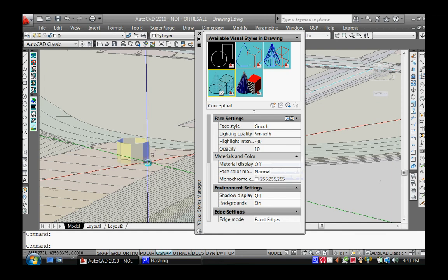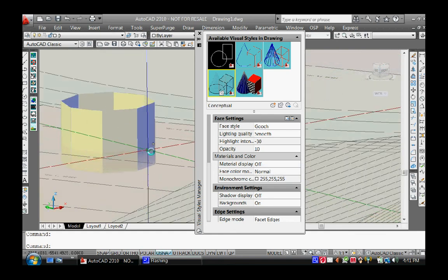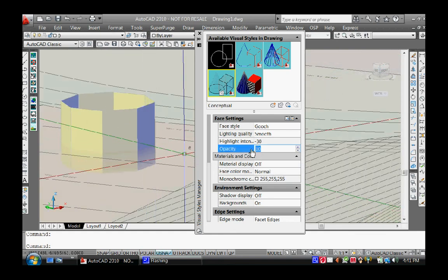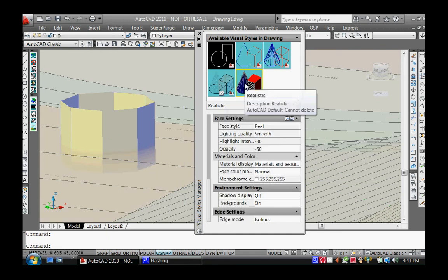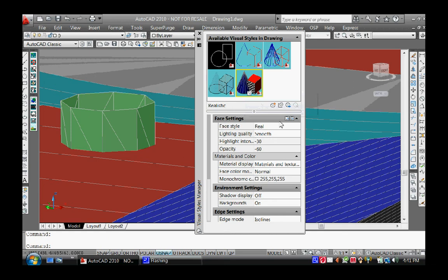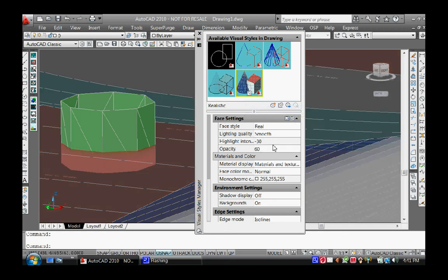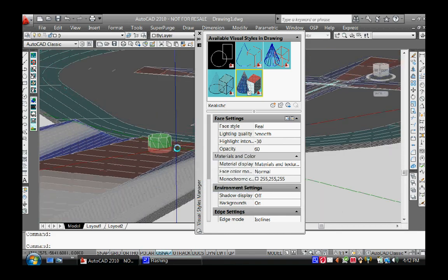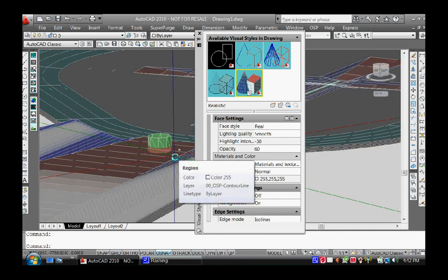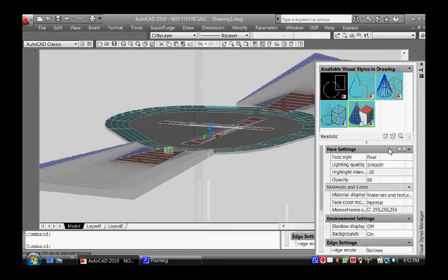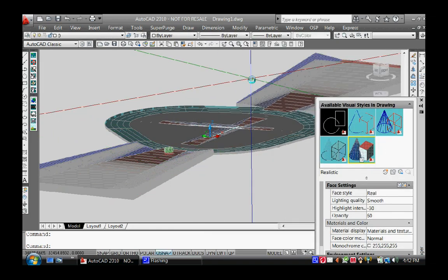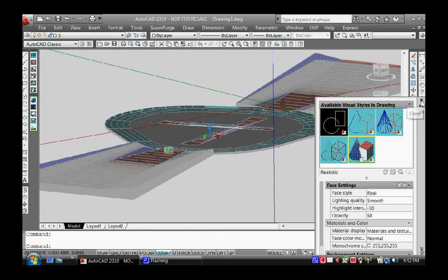You can kind of see the surface penetrating. Again, you can play with the colors and make this as fancy as you want. We can even make it conceptual if we look at the object that way and, there we go, give it an opacity of about 60. Something like that. You can see the object through the surface, and again, you can get as fancy as you want. You can put images under it. The program will detect different types of mountains. It'll detect any type of 3D object that you need for this project.